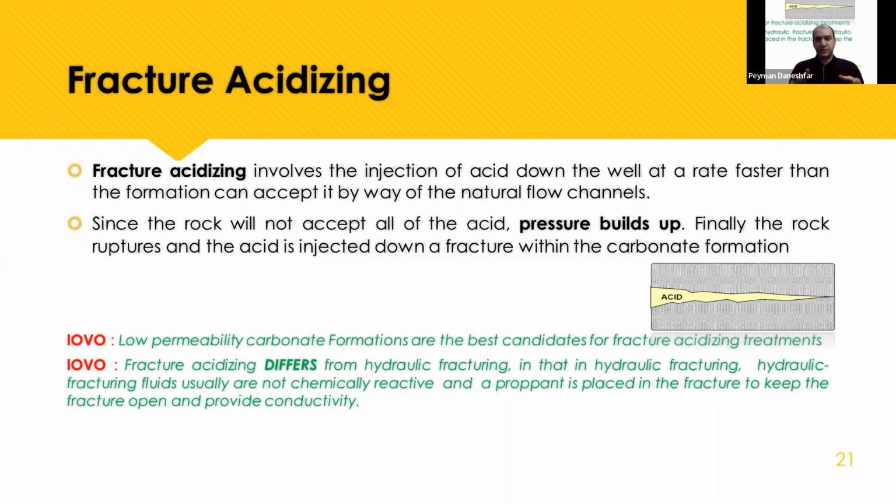But in hydraulic fracturing, we inject some special additives, maybe in fresh water, with some proppant that we inject into the well. Why proppant? We use a proppant to hold open the fracture that we opened before by exceeding the fracture pressure by injecting the fluid in our well.